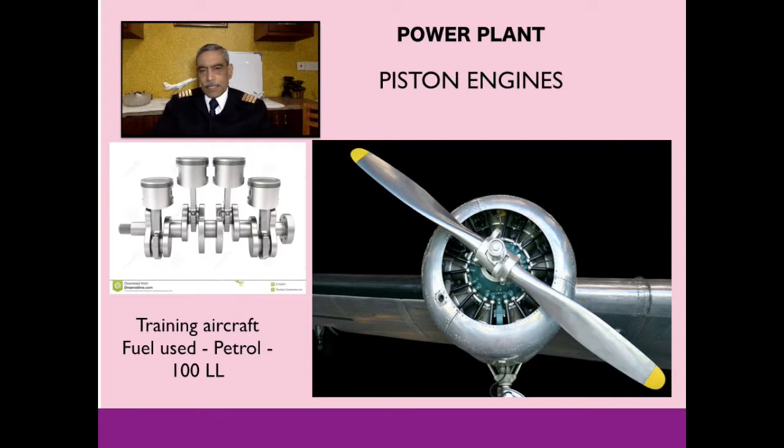Not very many planes nowadays incorporate these engines, but I must add at this point that most of the training aircraft incorporate piston engines, and it is fairly cost effective for a training aircraft. And the fuel used is normal petrol, slightly more refined petrol, called 100 LL, 100 octane, or 100 LL it is called.